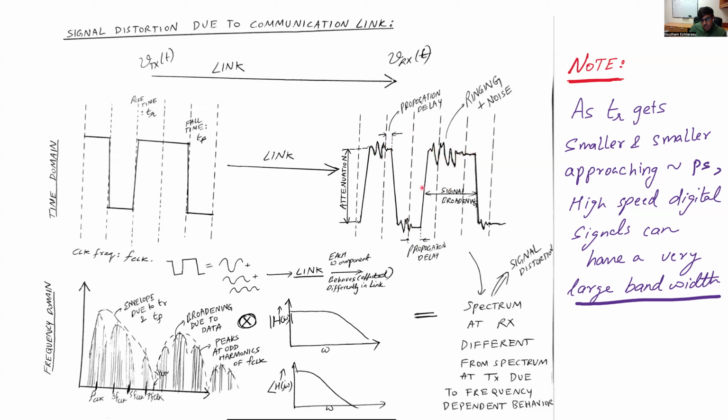So why is this an issue? Imagine we look at this instant. While the signal should originally be sampled as a 1, if the signal oscillates rapidly, as shown here, and the minimum value is very low, it can sometimes be sampled as a 0. So a signal that is supposed to be sent as a 1 is now going to be sampled as a 0, and now you're going to have bit errors.